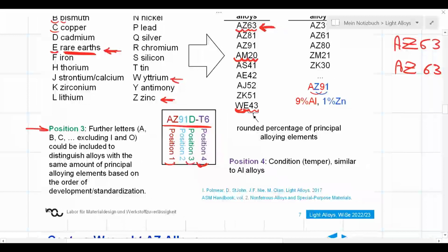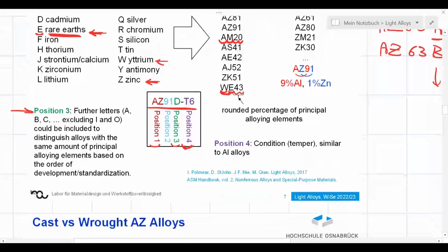This is something we have discussed in the context of aluminum alloys, so I'm not going to go through that. Perhaps some examples here. It indicates temper conditions, and T6, as we learned in the context of aluminum alloys, indicates artificial aging. So this applies to an alloy which is capable of precipitation hardening. We do a solution heat treatment, and afterwards we expose it to higher temperatures to get precipitates and potentially use precipitation hardening. In that respect, it is similar.